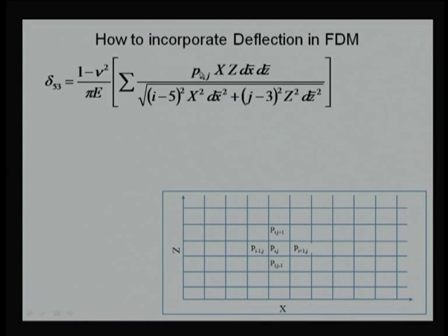Now, we continue with the same, and what is the difference when we were discussing hydrodynamic lubrication, the whole hydrodynamic lubrication equation has been represented in terms of non-dimensional numbers, and this is dimensional. We cannot simply combine non-dimensional with dimensional numbers. So, this whole expression needs to be converted to non-dimensional numbers. Now, to do that, instead of dx square, we can use a non-dimensional number, that is dx bar square, and there will be multiplication of the maximum dimension in x direction.